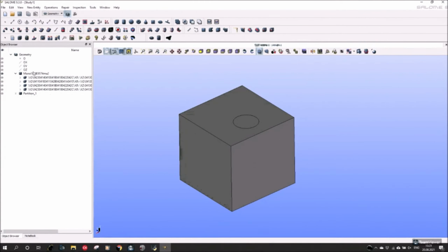So I didn't make a subtraction Boolean operation in the CAD system, for more comfortable and simpler work here. And this partition operation makes this cavity in the mold. So I see it here, and all contact surfaces were found by this partition operation. So now I have a fully prepared model for mesh generation, and I will go to the mesh model.